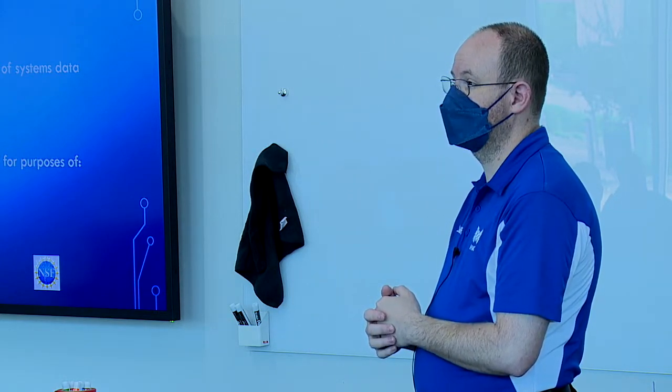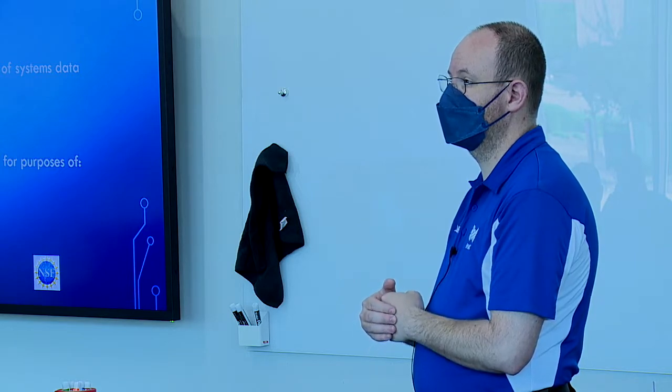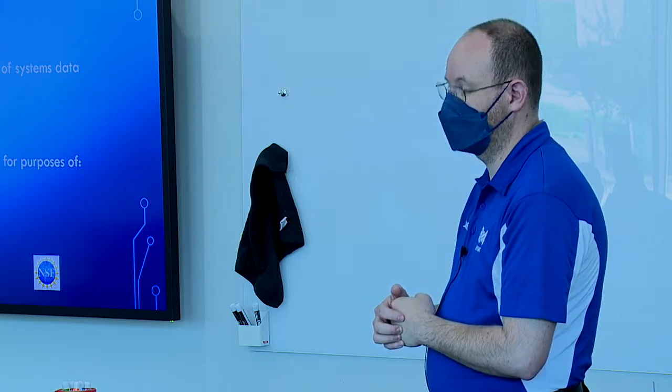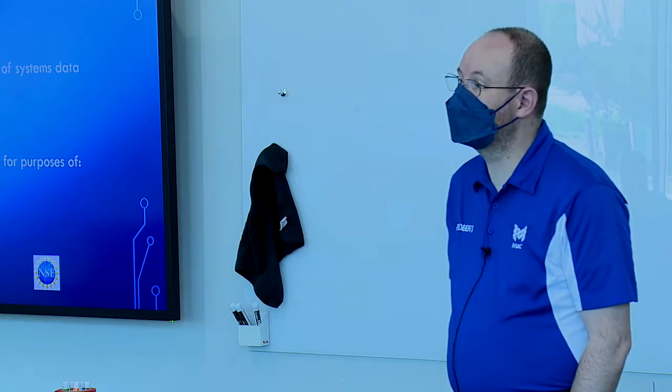That's right. The alarm should only be there, like space temperature, comfort cooling wise, never alarm. Use the trends to see if you have a problem. You only alarm for space temperature on critical areas, like cabin rooms or something like that. Never alarm on space temperature on comfort cooling, because who cares if it is actually out of line? You want to solve that problem by the historical trends you can look at, but do you really need to know? I mean, the document's going to tell you. True. So, minimize alarms is really the key.